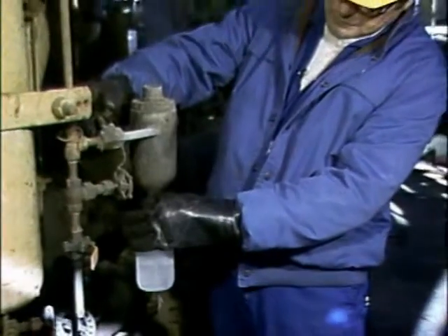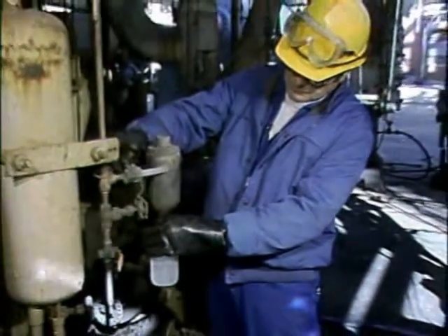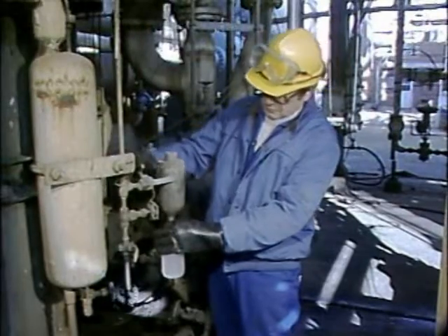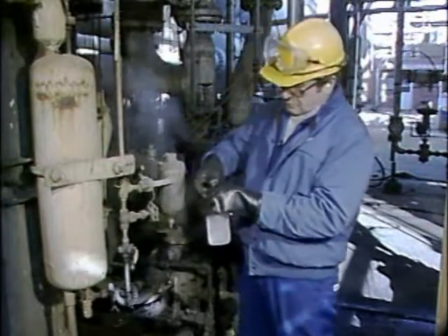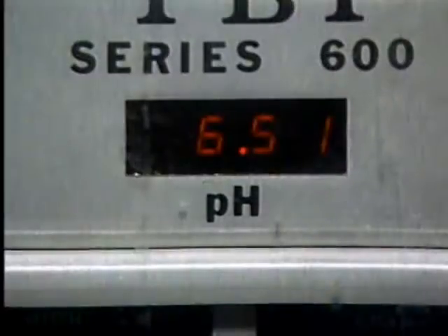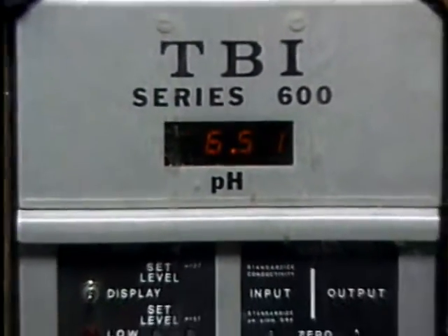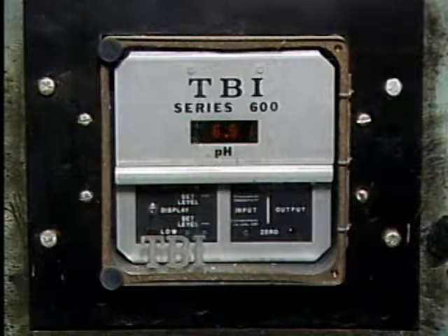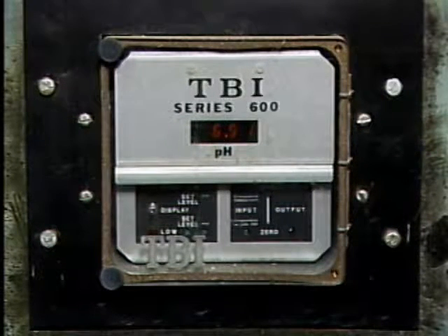One way to check for contamination is to take a sample of the lower pressure fluid and test it for the presence of the higher pressure fluid. In some cases, contamination in the sample can be seen. In addition to sample test results, conductivity and pH readings of cooling water may indicate a tube leak. If there is any indication of contamination, it's important to determine the source of the problem and take the appropriate